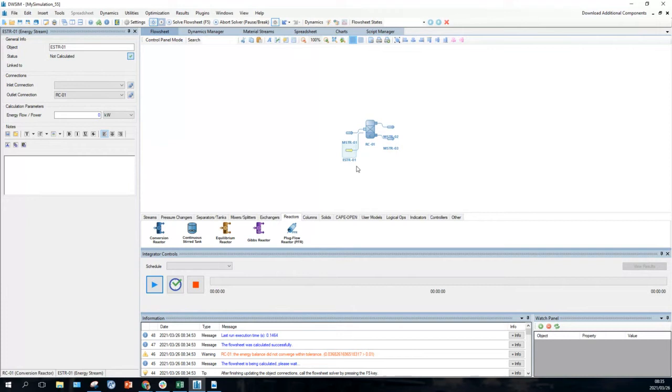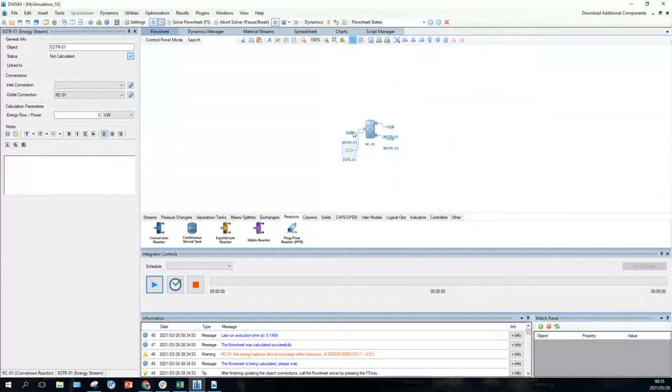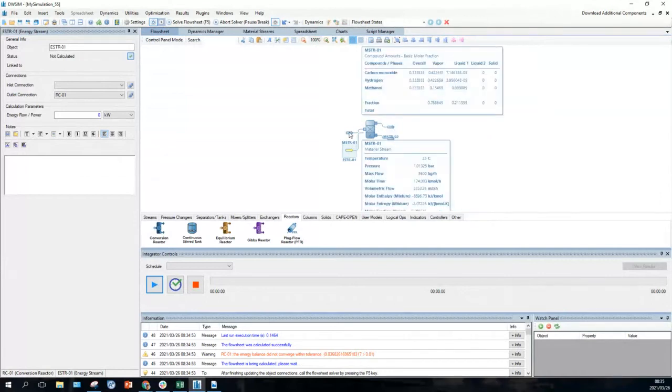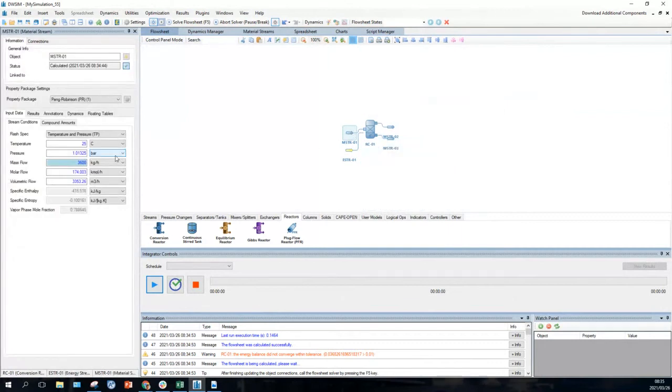So the next thing we need to do is to add the reactions. So now actually you're going to find that these things are going to have the same inlet. Oh, no, we're not going to do reactions yet. We're going to first change the inlet composition. So this MS3R, it hasn't changed from the inlet. So let's change the inlet. Click there, get our inlet on this side.